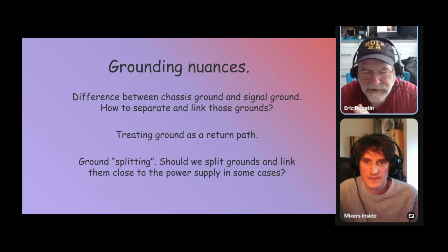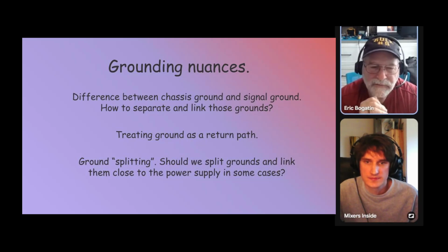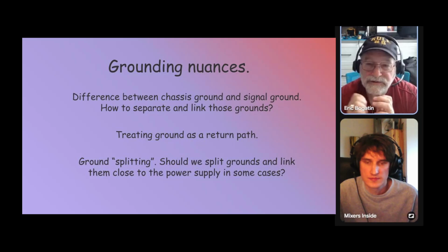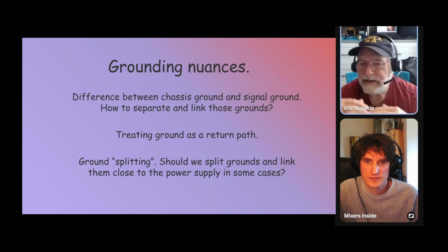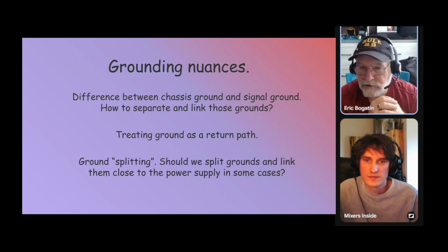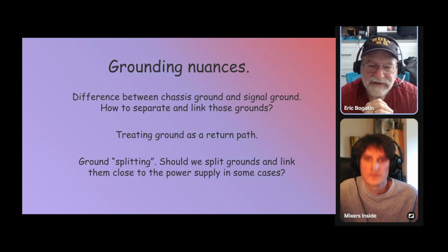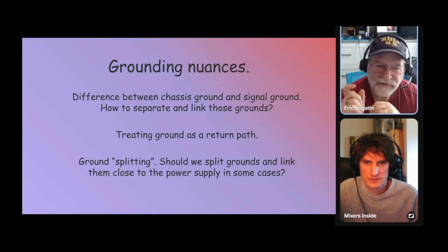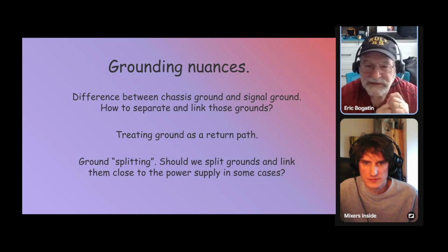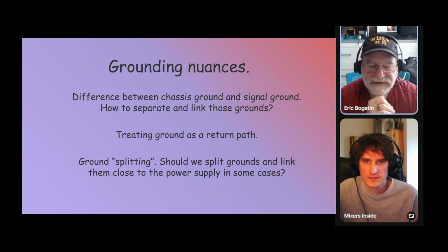And so when we do the layout, we want to be thinking about where the return currents are flowing, and where possible, maybe use a separate trace as a reference voltage that is assured to not have any current flowing in it. That effectively is like a differential pair. It's having a signal line and a reference. Think about the interconnects from a microphone, for example, or an input that's a low-level signal.